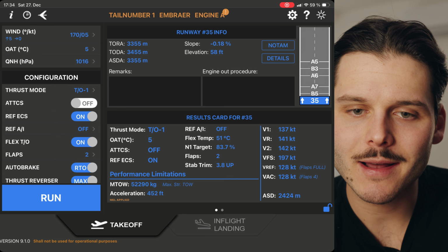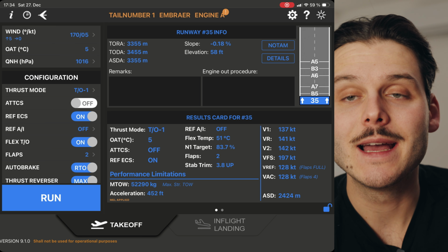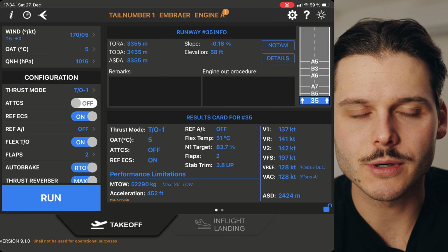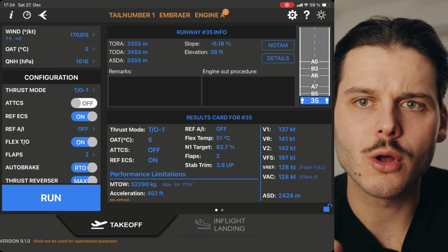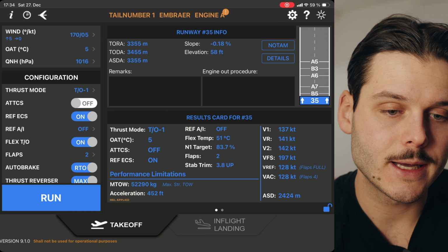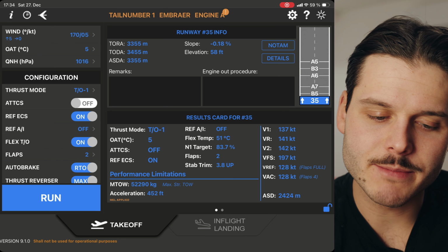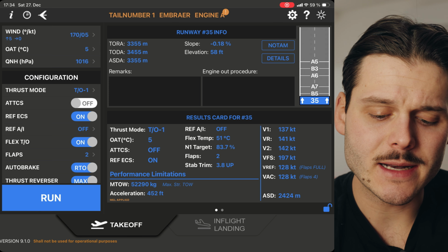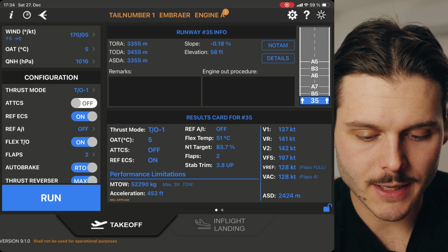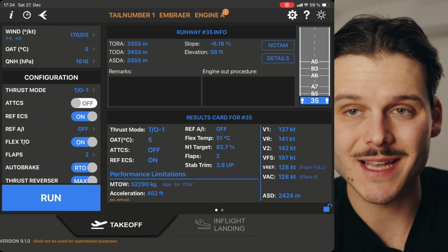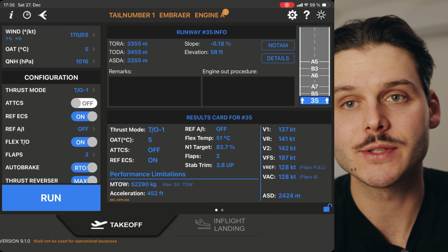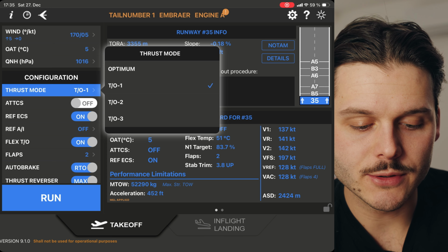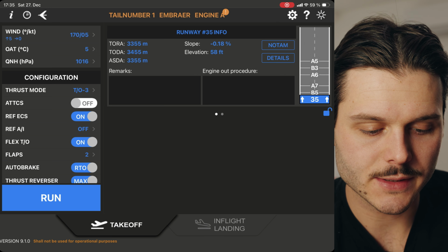The A320neo that we recently acquired here on my airline is flying to destinations primarily like Amsterdam and London, not because you save so much fuel, because it would be much more logical to send that aircraft to longer routes like Tenerife or Iceland, but actually because you save so much money on landing fees. This is why you need those neo aircraft, and this is also why you do flex takeoffs, and also to reduce engine wear, because the higher the exhaust gas temperature, or the internal turbine temperature, the higher the wear of the engine. So this is how you can reduce your engine thrust even more.